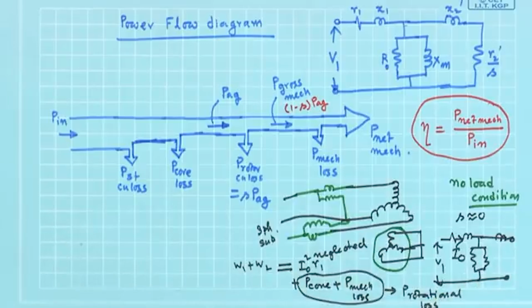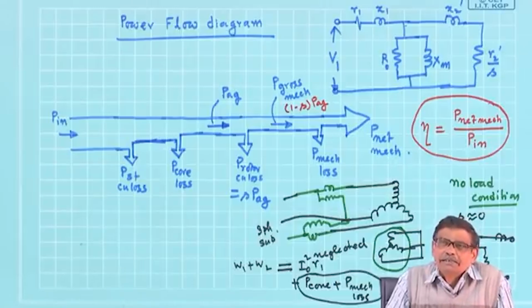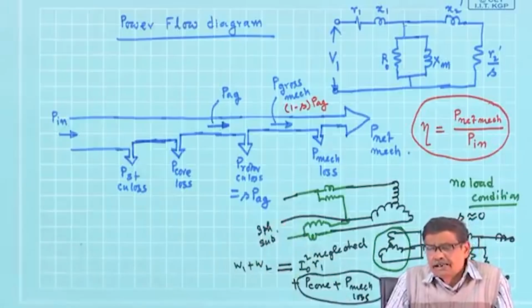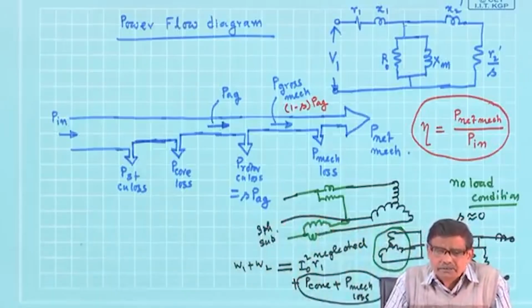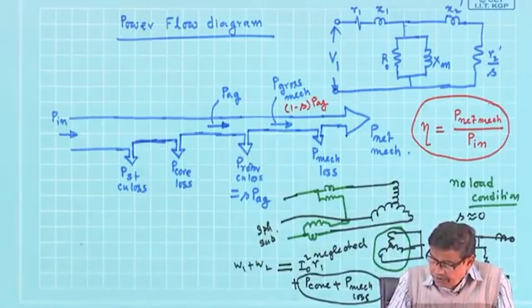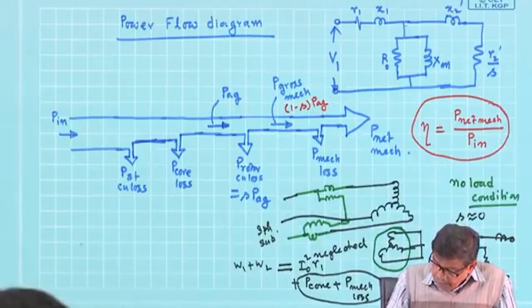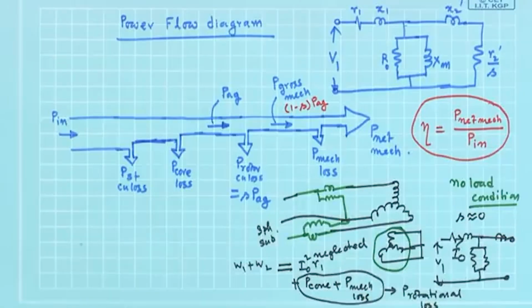in an induction motor from no load to full load condition, mind you this statement, the change in speed is how much? Very little, 5% slip, little change, maybe 70-80 rpm from no load to full load. Do you think the frictional loss will change because of this? No, it will practically remain the same, because it is running against air, and bearing friction will be similar. I mean, why should there be a difference? Because the speed variation is less. So, the frictional loss remains the same.